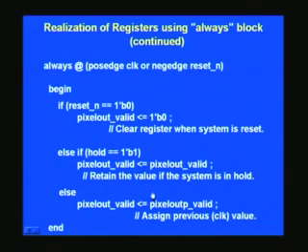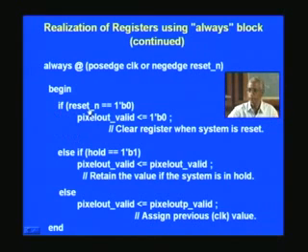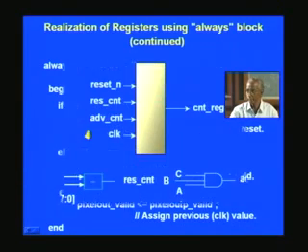Before we wind up with this example, we'll see what it implies. If you write an if statement, what it puts in hardware is a mux, and all of them are put as muxes. That means one mux output cascades into another mux and so on. That is the reason I said you should restrict this to say 4 or 5, based on our experience. That would ultimately decide what frequency of operation you get, and that is an important thing to keep in mind as a designer. We will go on to the next example.